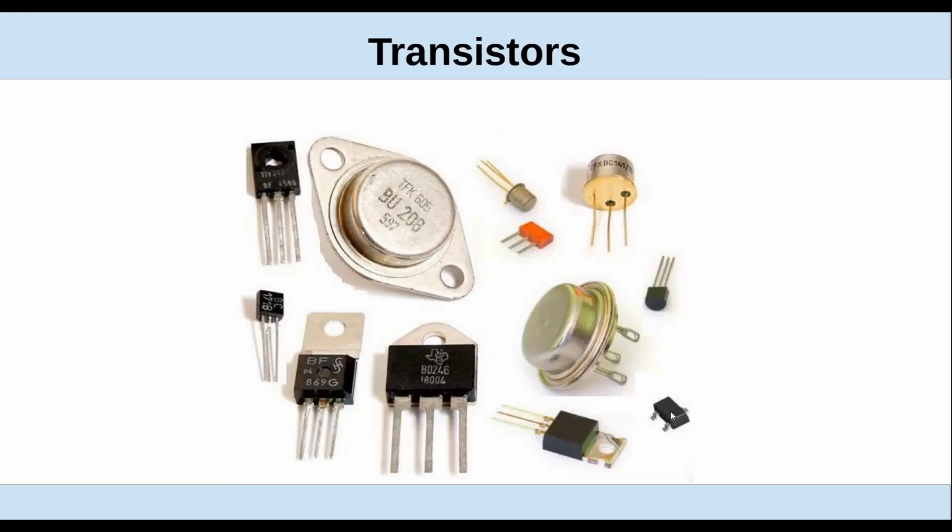It's not exactly a flat pack, and it's almost a surface mount. It's a little bit bigger than some of the really small ones. These with the tabs on them are also power transistors. And that's how they get the heat out. You attach that to some sort of heat sink because they do dissipate a lot of power unless they're in switching mode.